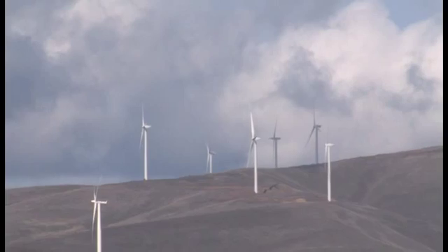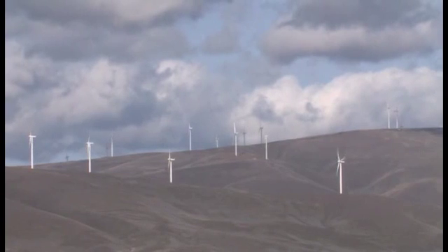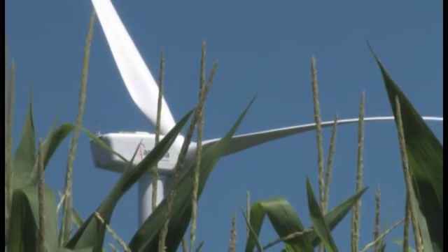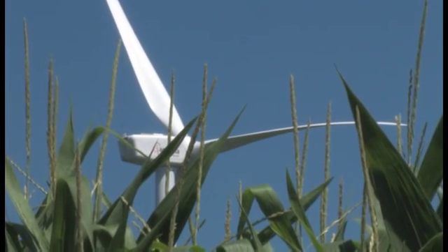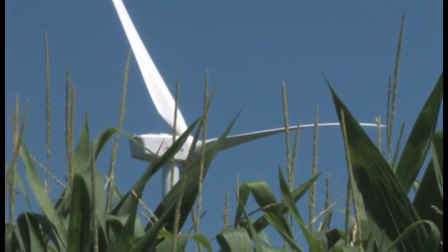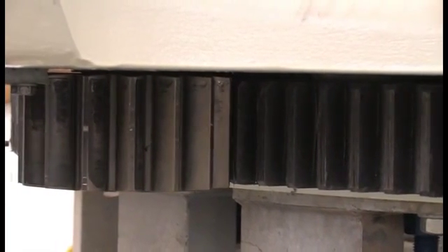During normal operation, when the wind speed is above 3 to 4 meters per second, the controller will keep the nacelle pointed into the wind and make corrections as the wind changes direction. During times of low or no wind, it is not necessary to keep the nacelle pointing into the wind. In fact, tracking a wind that is too low to produce power results in unnecessary wear on the yaw system.